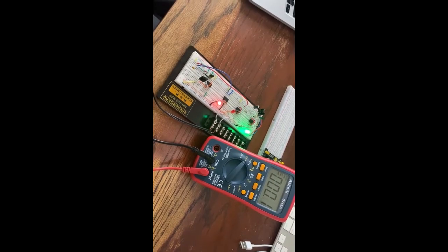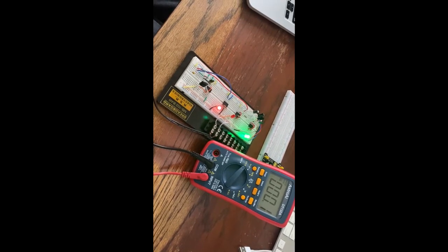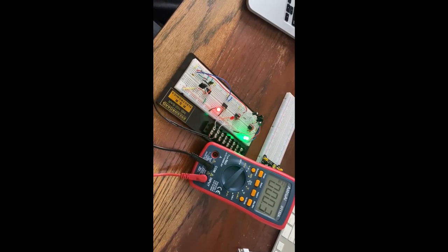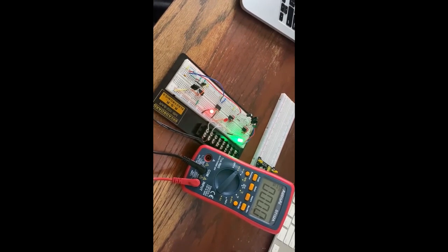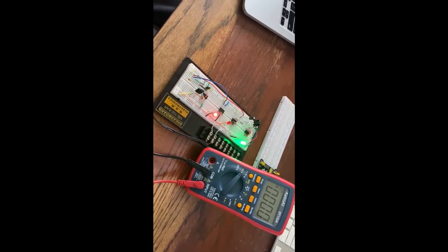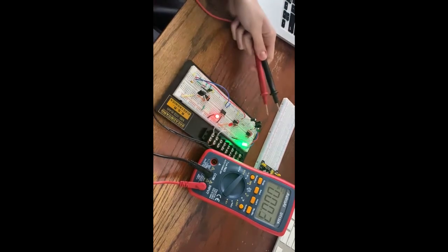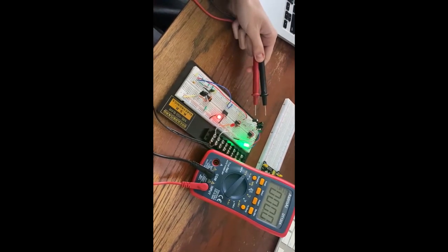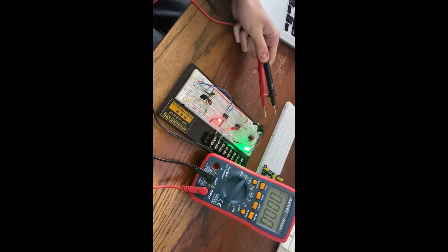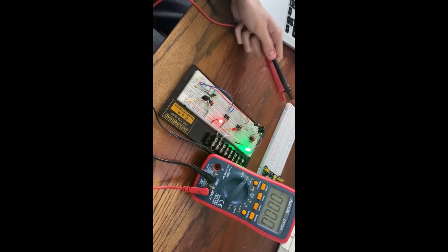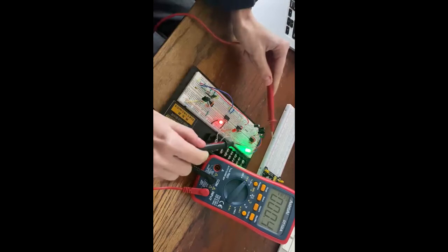This is the load integration and measurement subsystem. I've designed an electric meter that has a voltage and current sensor. The current sensor requires 10 volts of input supply power, and how I've done that is I've designed a voltage rectifier or a voltage doubling circuit using a capacitor charge pump and a 555 timer integrated circuit. I'll demonstrate the voltage doubling now.